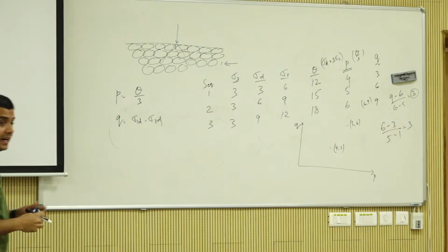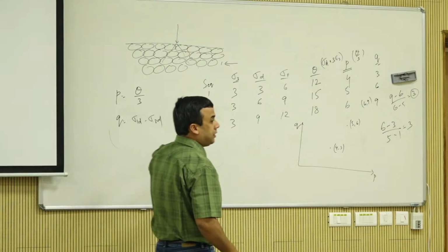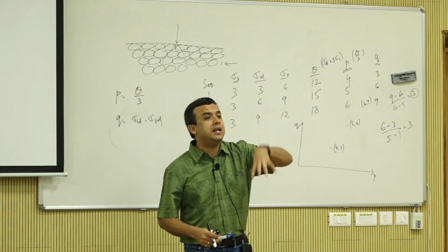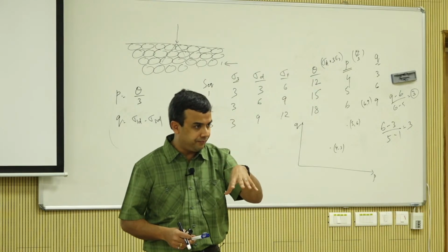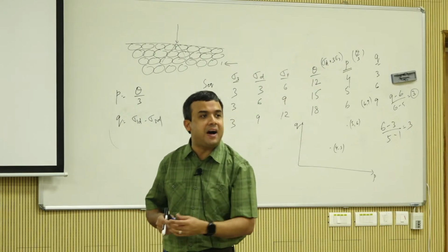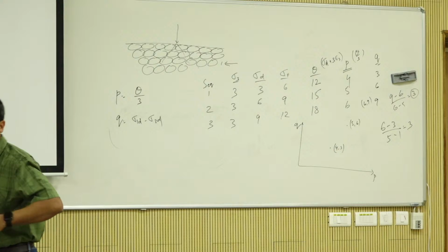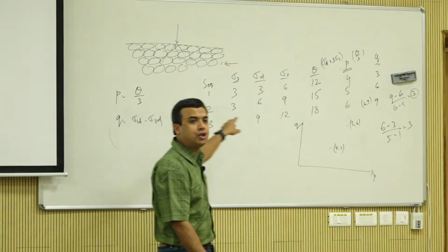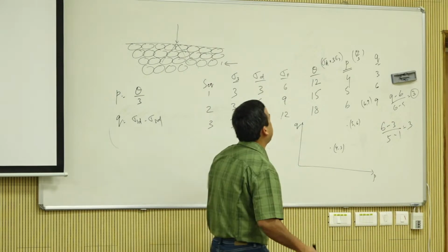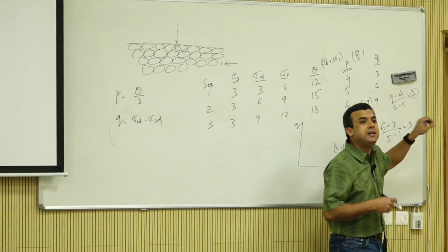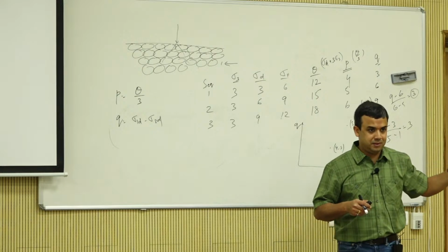Okay? That is what you are subjecting it to when it is vertically on top of you and you are actually just pulsing. In the advanced triaxial testing, what we are saying is that it is not always vertically on top of you. So you should not be pulsing just vertically. So your stress path slope should not be 3 all the time.